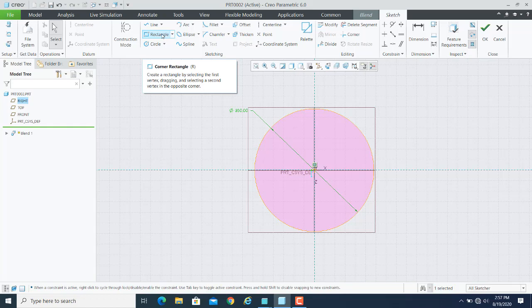We did cover all other options, but circle to rectangle, circle to pentagon, or circle with multiple edges option, we did not cover that. So suppose I want to make next section as a rectangle, or any other closed entity. So suppose our next section will be a rectangle.